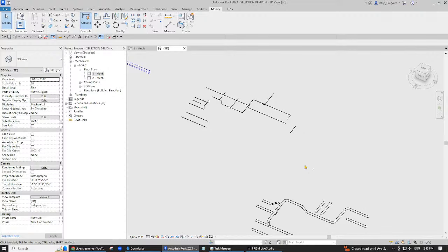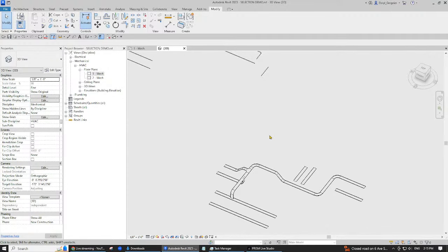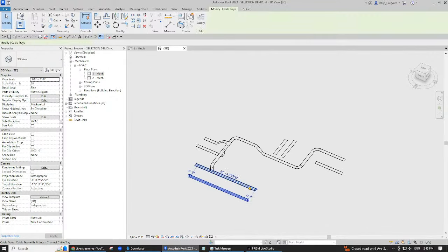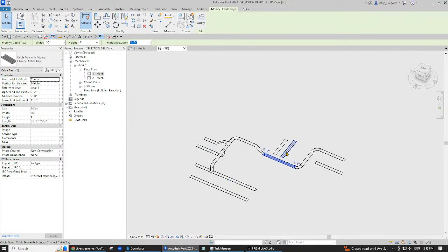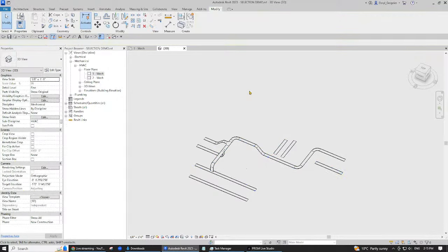So in here, I want to talk about selecting. So first of all, you can select, and when you select, something else disappears, right? If you hold your control button in, you can pick more than one option at a time. If you hold your shift key in, it removes it. So control adds, shift removes. Now you can also click out to clear your selection, or you can click the modify tool to clear it.